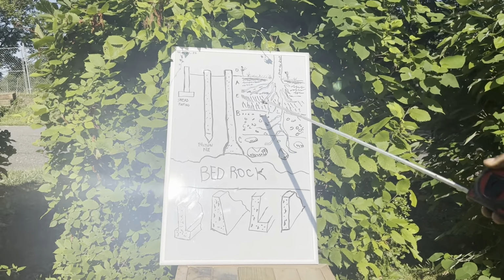Okay, you want to go past your organic matter right here, or your topsoil. This is also called your topsoil. Go past that and go down into your profile. Now, you see how sticky this soil is? And look at the color of it, that tan color and almost orange color right there, okay? And look, it's sticky.